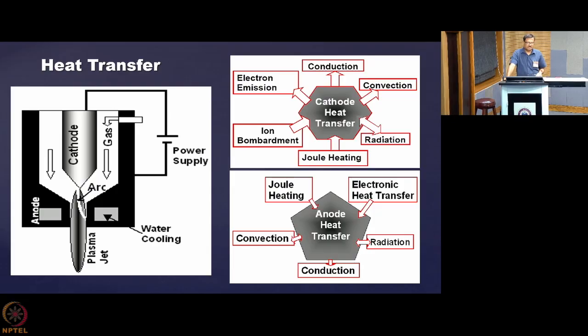So, it is very easy to calculate from the rise in temperature of the coolant as it passes through the device. Similarly, the cathode needs cooling. If you have additional segments downward, those also should have cooling. So, the more segments, the more cooling you require, and the more heat is extracted through the water. So, that is a loss.